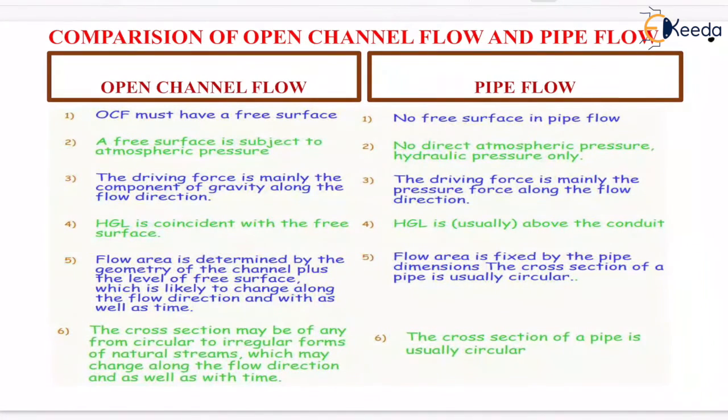Now, in case of open channel flow, the driving force is mainly the component of gravity along the flow direction, and in case of pipe flow, the driving force is mainly the pressure force along the flow direction. Now, the hydraulic gradient line is coincident with the free surface in case of open channel flow, but it is usually above the conduit in case of pipe flow.